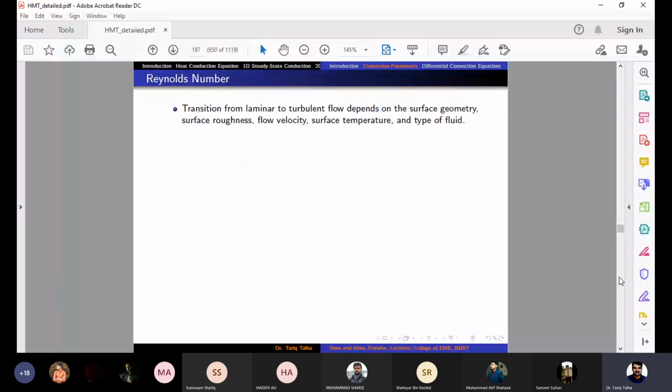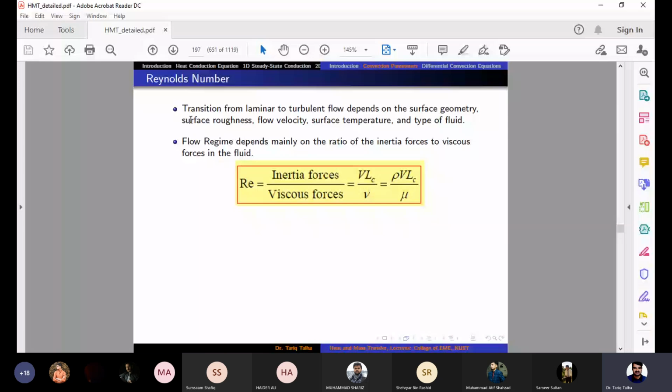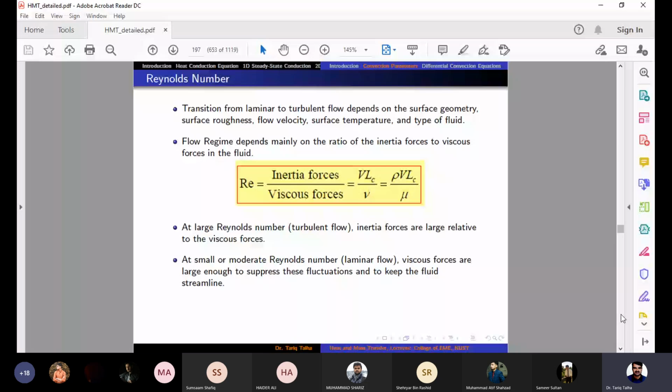This is just the revision which we discussed in the last class. First of all, there are three parameters I discussed. Reynolds number: we all know that Reynolds number is the ratio of inertial to viscous forces, and there is a critical Reynolds number below which the flow is laminar, and beyond that the transition to turbulence starts. For pipe flow, that value is 2200. For boundary layer flow over a flat plate, that value is 5 lakh, or half a million.